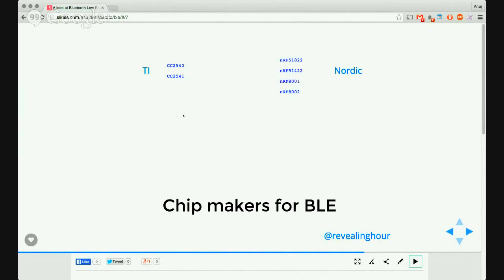So these are the four system on chips and ICs which are available from Nordic for Bluetooth low energy. The first two are system on chips. That means that they are very well packaged, and the Bluetooth low energy IC is not the only aspect of it. They have something else known as the programmable peripheral interconnect, which allows them to connect to a multitude of sensors and get that data and provide that data over Bluetooth low energy. The third and fourth are pure ICs, and you have to take care of designing the whole circuit so that you can connect such sensors or a microcontroller or something on those lines.